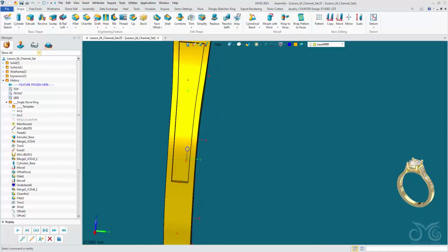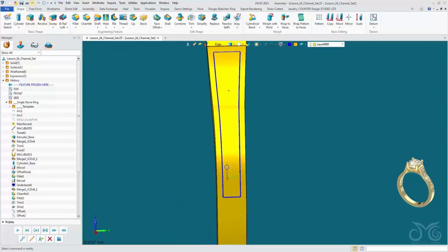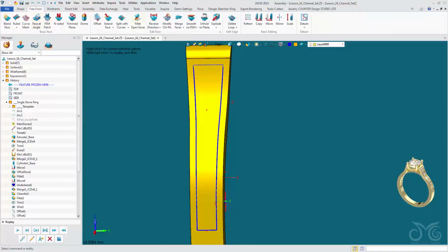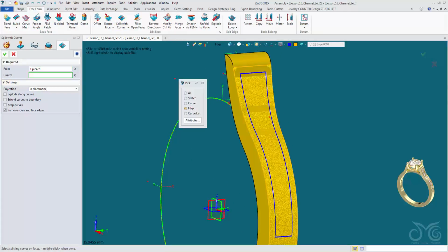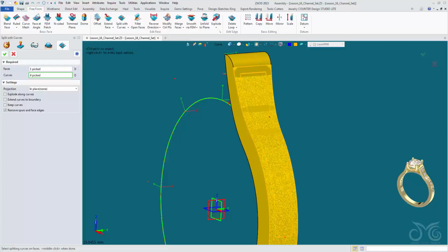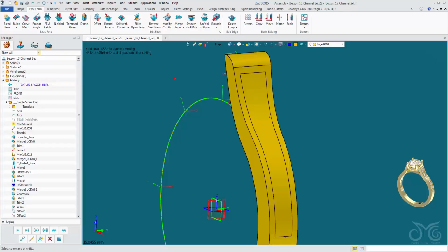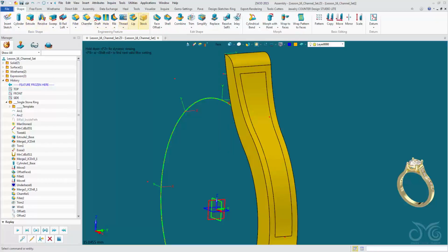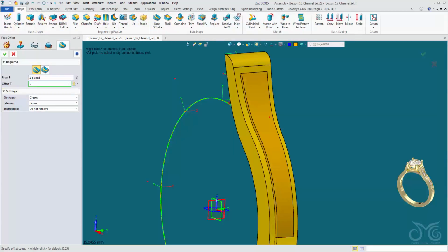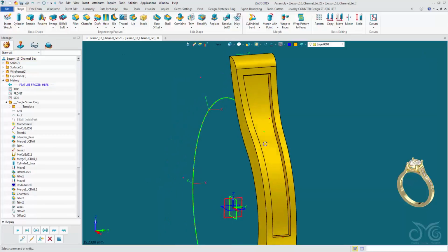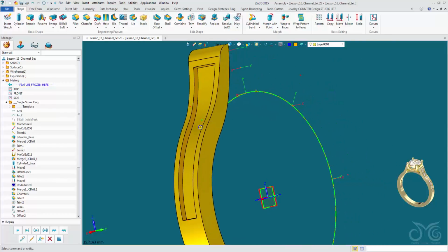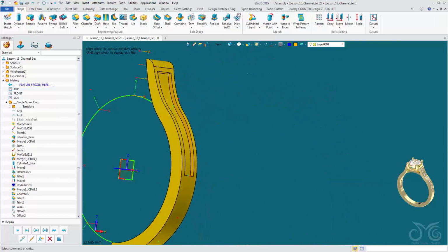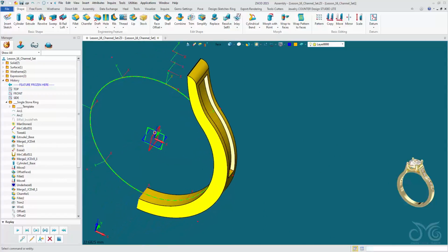If for some reason the inlay didn't work, you can approach this differently. Undo the inlay, come into the freeform tab, split with curves, pick the face, the curves, we can shift, chain pick them again, confirm the operation. There we've split that face with the curves, and then we can perform a face offset, negative 0.5. Okay, so either method works there, either the inlay or the split with curves and then the face offset. Sometimes one method may not work, so you've got alternatives.